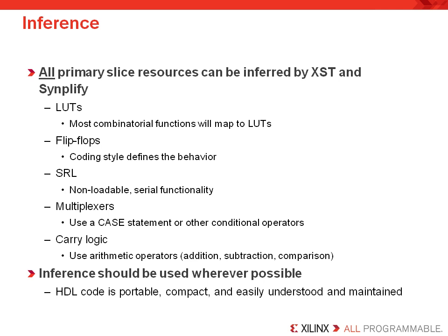Likewise, the shift register LUT is non-loadable, has no reset, and only supports a serial functionality. So if you code for a parallel read, you'll get a pure register implementation, and this again may not be what you expected. Similarly, muxes need to be coded with a case statement, and carry logic should use the proper arithmetic operator. Don't code for the XOR functionality if you're targeting the carry logic, otherwise you just won't get it.